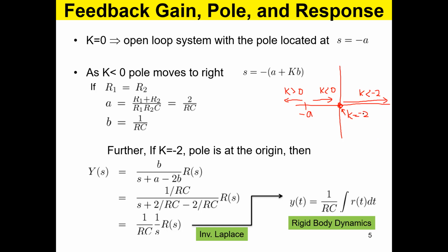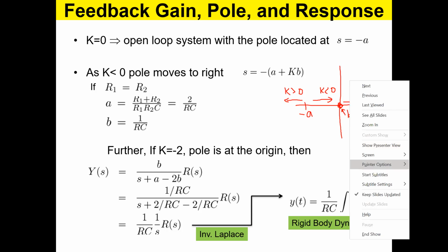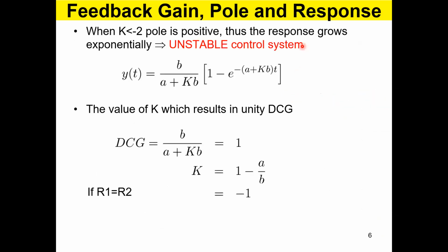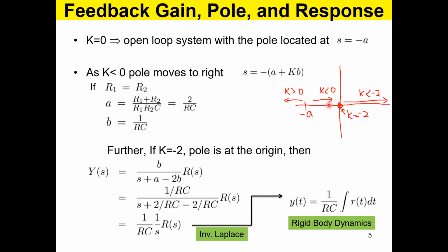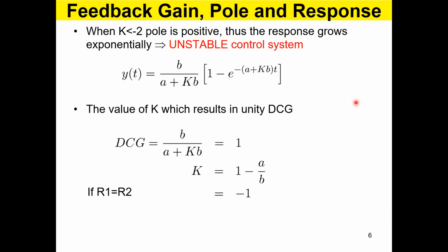Beyond that is worse, which means the pole is positive. Now you can have negative poles, you are happy, there is no stability issue. Pole is 0, you have some concerns. And pole on the right hand side, positive, you have serious problems. The system is unstable.